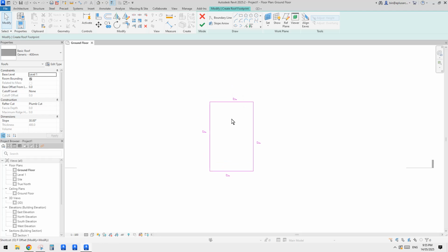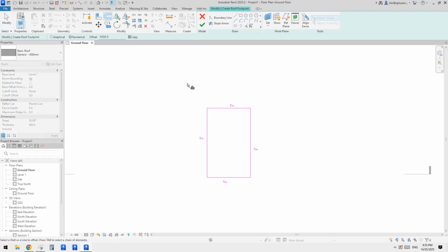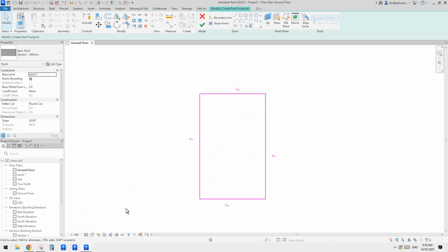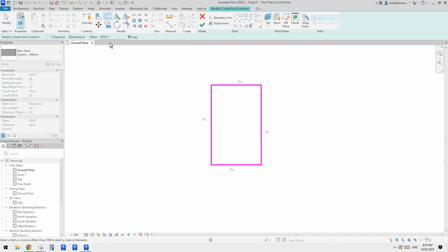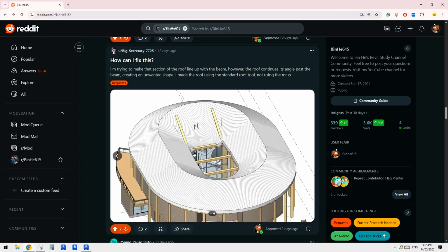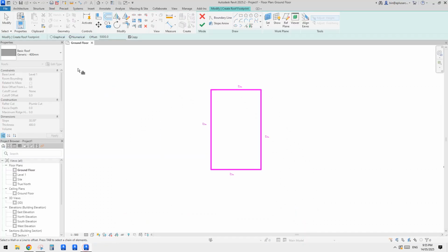That's in the middle. I'll use offset. Maybe let me just TL first. Maybe change the scale a little bit and TL again. Oh, doesn't work. Maybe the scale's not right. Okay, so that's better. OF offset. If that's 5 meter, this is about 7 meter. So let's try 6 meter.